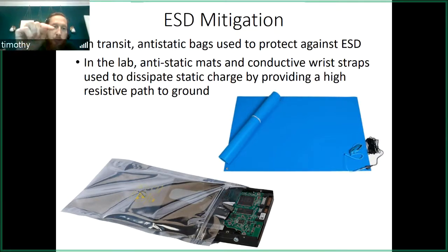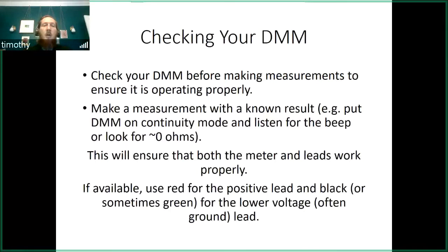However, I've noticed people that have used this anti-static bag for the mat. Do not do that. The anti-static bag actually will transmit the voltage. So do not use that as your mat. The anti-static bag is what you use to put electronic components in. The anti-static mat is what you put on the table. Don't mix those together.